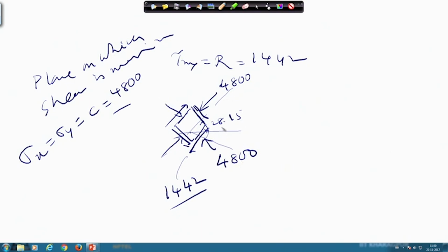So, this is the orientation, that means the maximum principal stress was here in this direction, and with this the shear stress will be at 45 degrees. So, how much, that means we have to rotate from here, I will take 28.15 degrees, 28.15 plus 13 point something, that becomes 45. So, with this orientation I complete the element, on that element now I have shown the maximum shear stress and the normal stress on that plane also. So, this is the third part.